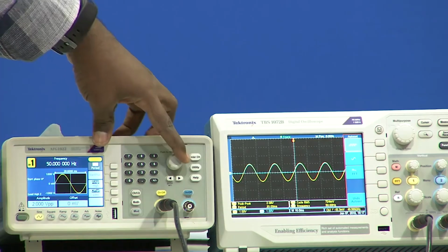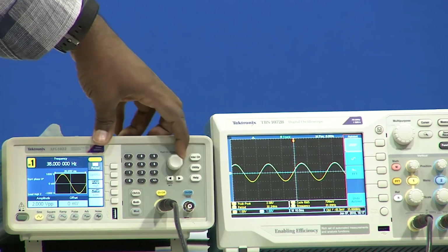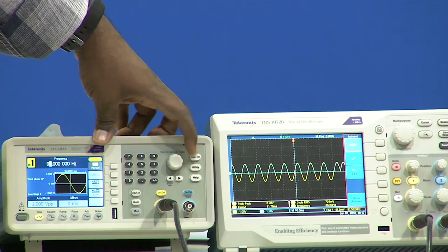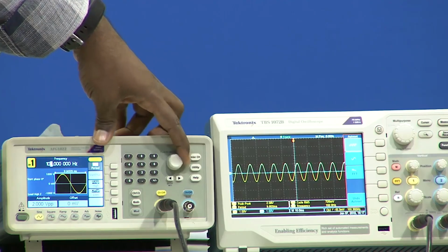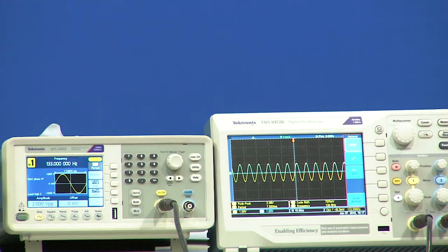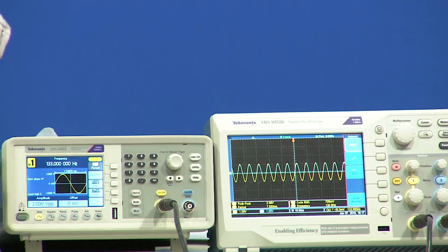Even if I change the frequencies, no matter what frequency you are at, it can only pass the positive input signal, not the negative input signal. That means whatever we have seen in the simulation and what we are seeing in our experiment, the half-wave rectification is completely done. Now, what is the next part that we have to see? After passing through the half-wave rectifier, we have to find out the peak.